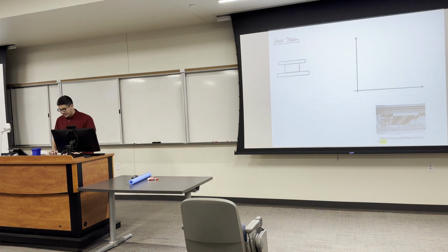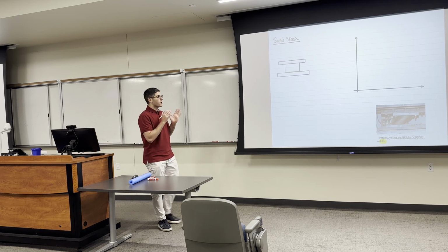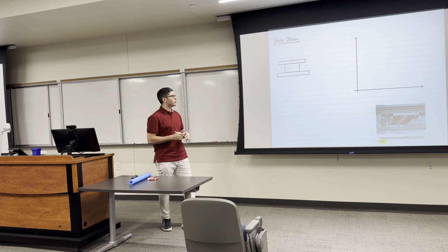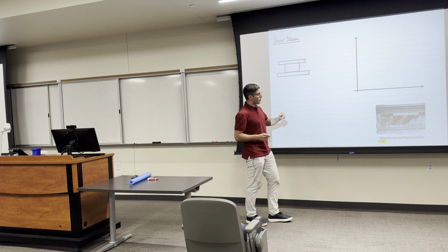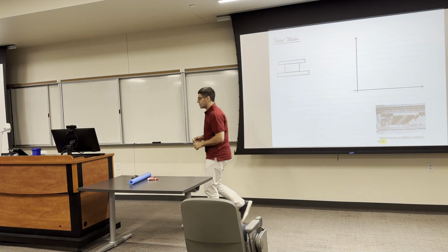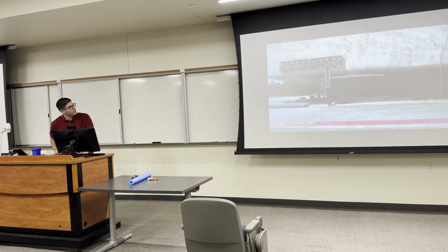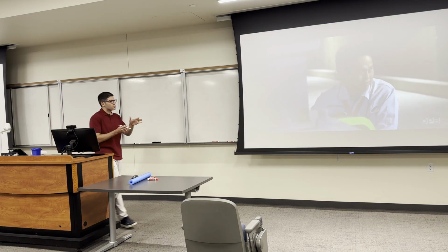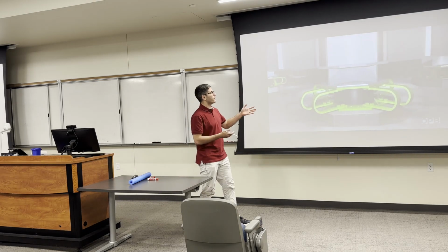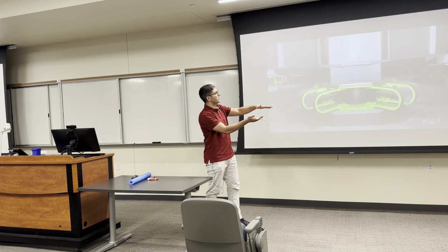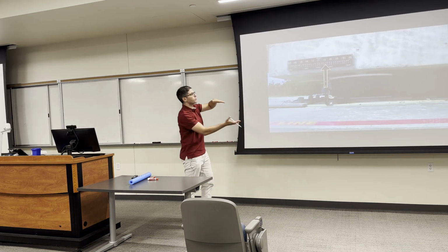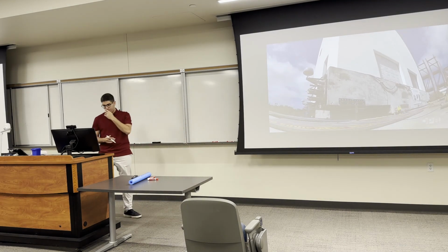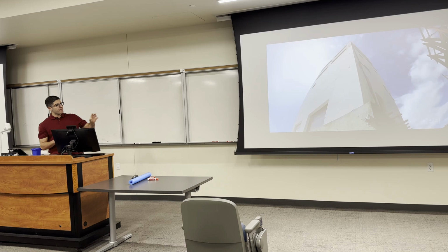Let me explain one last thing, which is the shear strain. When we have a deformation that's parallel to the cross section. So I have this bearing, and I will show you a video that explains what's going on here. This is what we use in earthquakes. This is something we put under a building to absorb the earthquake force. So this is how it moves. If this is the cross section here, it moves parallel to the cross section. Okay? So this bearing is actually having a shear strain.